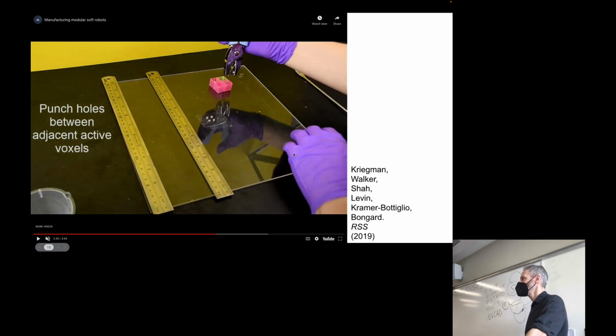Why the hole punch? To allow air to come in and out. Absolutely. So we're going to supply air in and out of this voxel bot. By punching holes in certain walls, we can guide where the air is going to be, and in that way, indirectly force sets of contiguous voxels that are attached together as neighbors to all increase and decrease together. And we can punch other holes that connect another subset of voxels in the same body to also increase and decrease, but we can pull air out of one part of the voxel bot's body while we add air to the other, and vice versa.